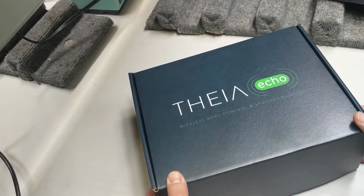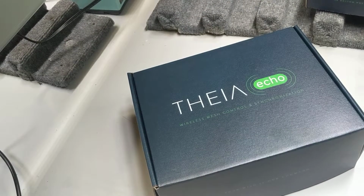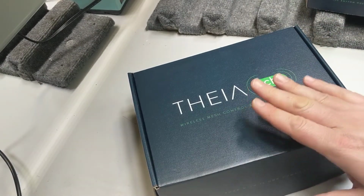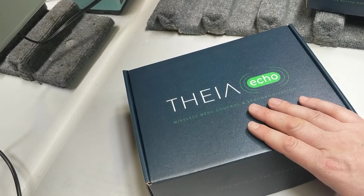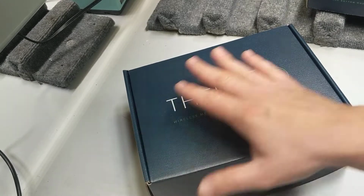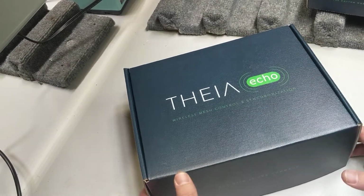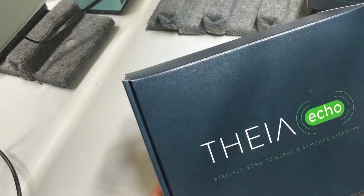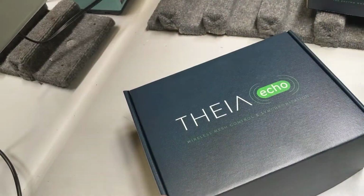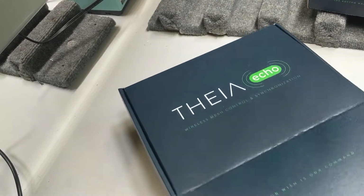Okay, here is the other one. This is the Echo. Now, this one does everything that the Tempo does, but it does one other thing. This one is needed if you need our lights to take a dimming command from a third-party environmental controller. So if you're using, on the advanced side, like an Argus system or maybe a Trollmaster on the other side, a couple pretty common products that we see, this will actually take a 0 to 10 volt dimming command and will share your dimming command wirelessly with the group. So let me show you this.